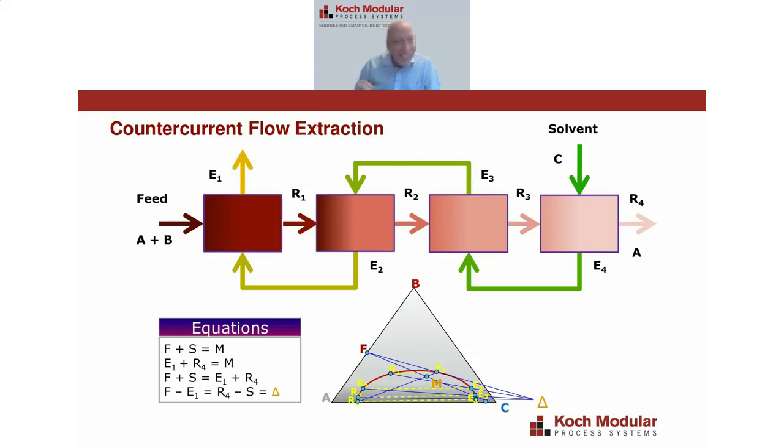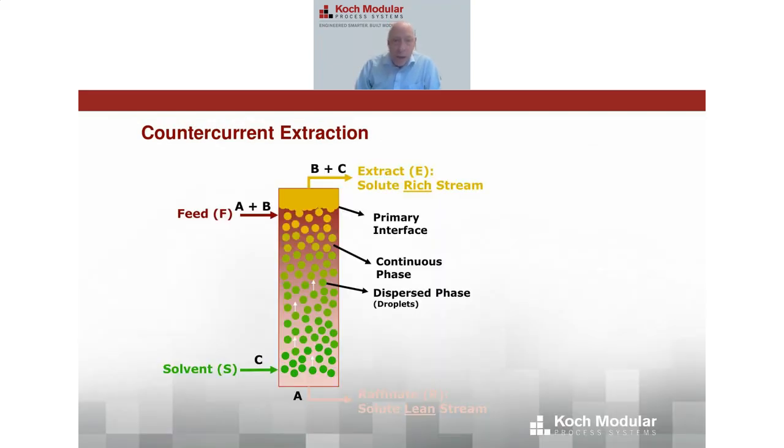But what you've obviously done here by running countercurrent is you're using only 25% as much solvent in this case as you would have used in a batch process. And now that solvent needs to go downstream and typically be recovered often by, say, a distillation process. And then the bulk of your energy cost is not in the extraction process, but it's going to be in that downstream distillation process. So that's certainly the idea of an extraction column, is to bring your feed in one